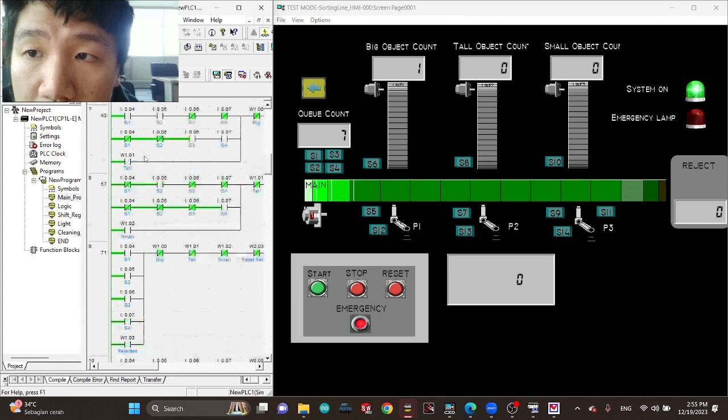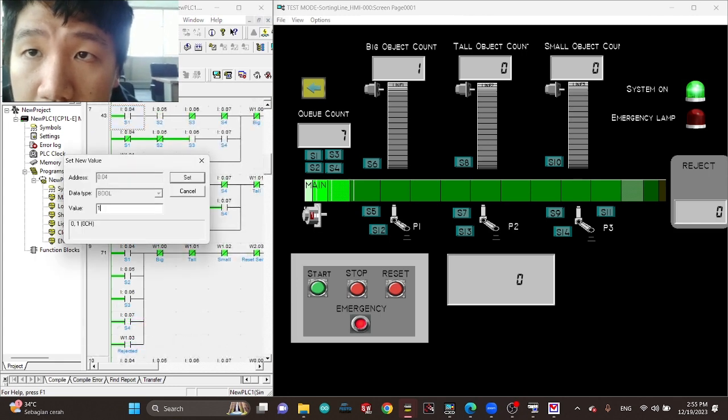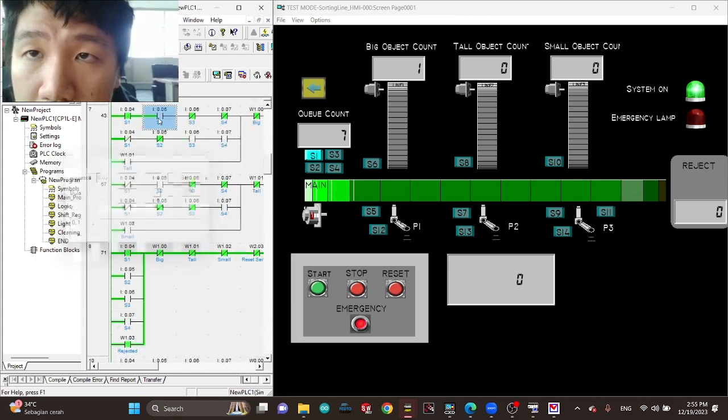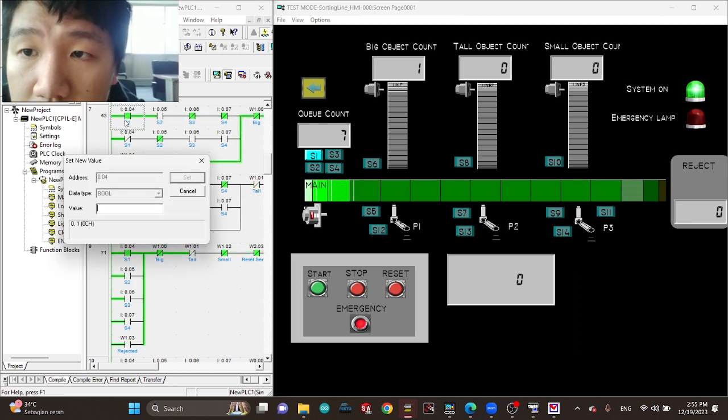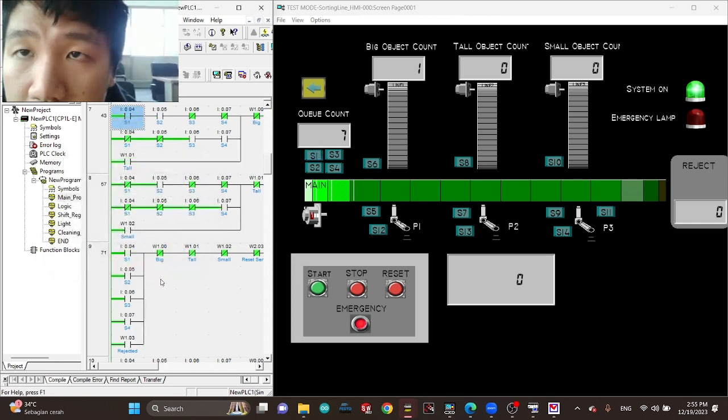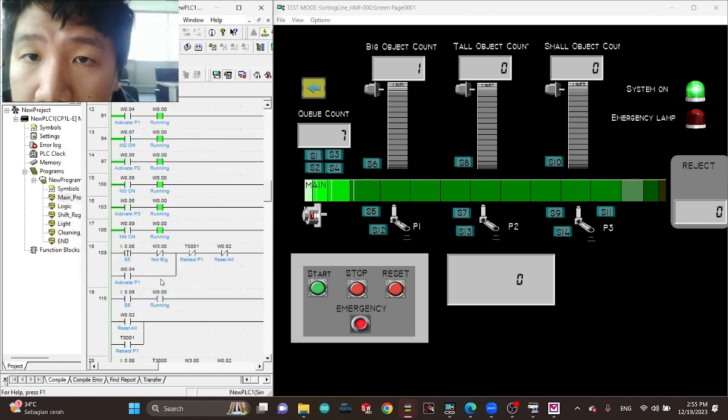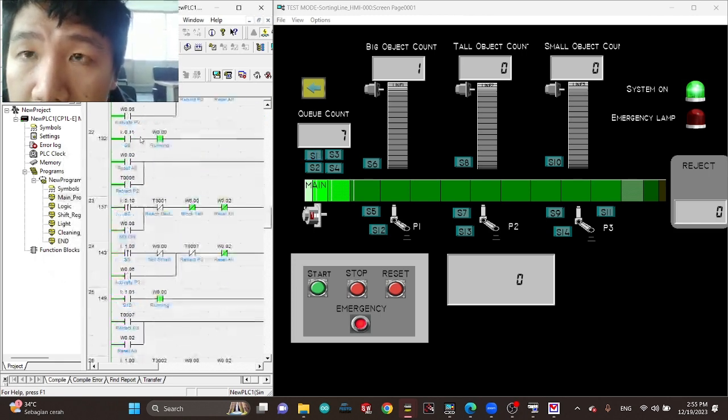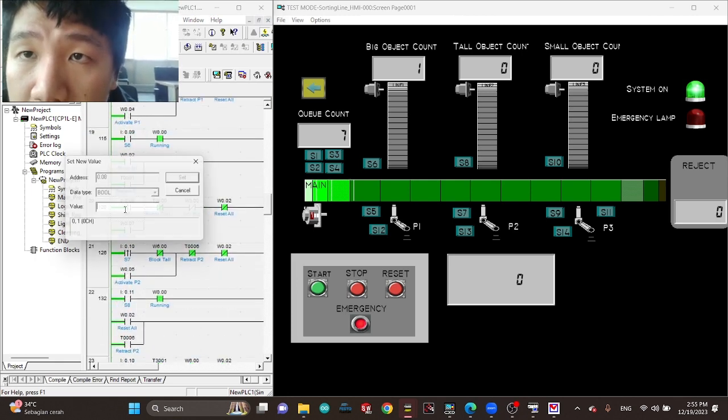Then moving on, I'm going to test now the tall item, which the requirement is S2 and S3 or S4. The sensor detects S1 and S2, and the item is leaving. When the item is leaving, it will give the input that it is a tall item. It will move to S5. The sensor will detect it at S5.